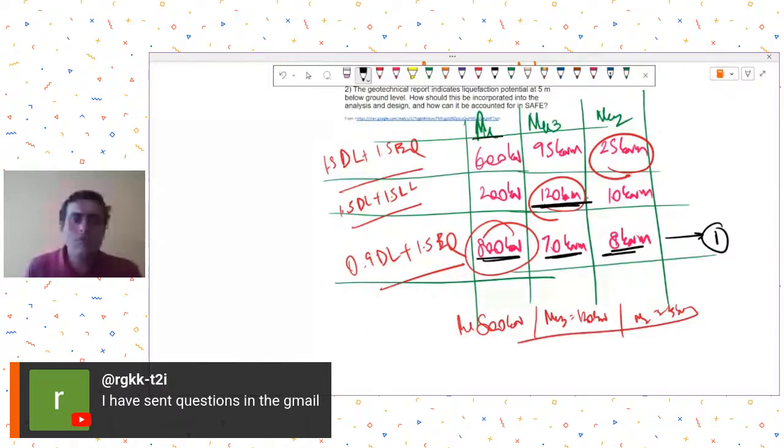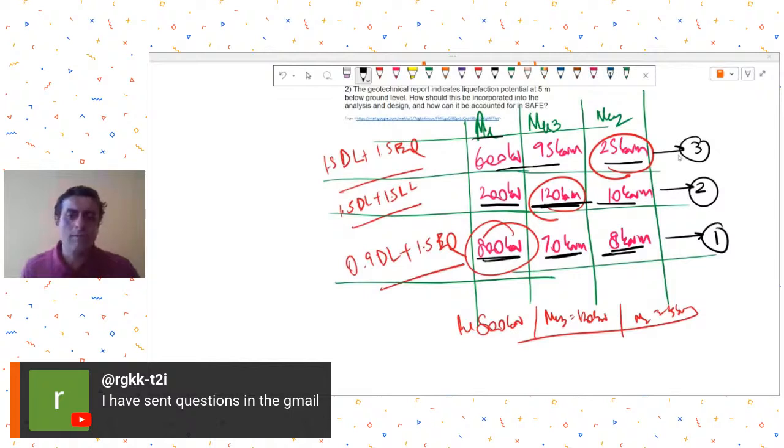So then you consider the corresponding values, that means in the same load combination, take the other two values and perform your design twice, two times. And for the other action again, perform the design three times. So taking envelope values is incorrect.